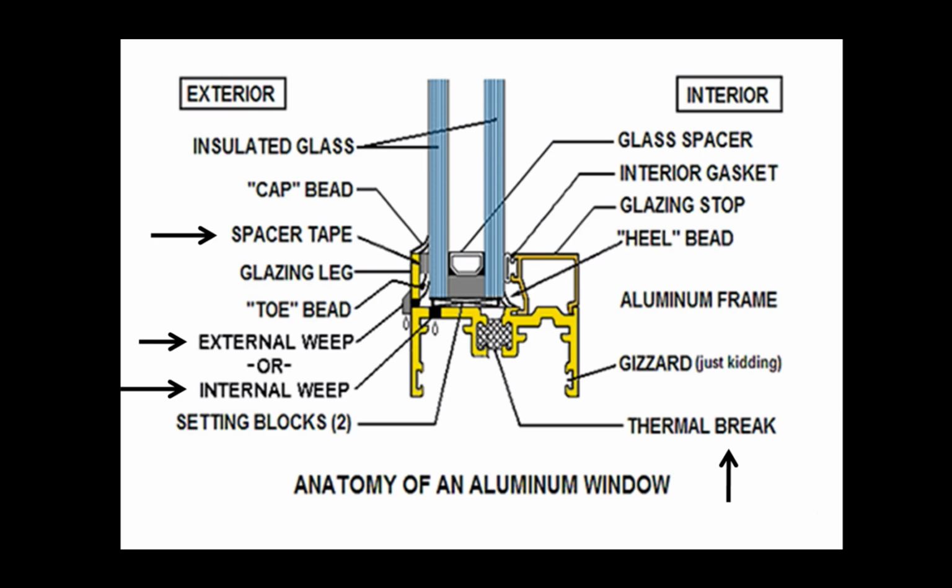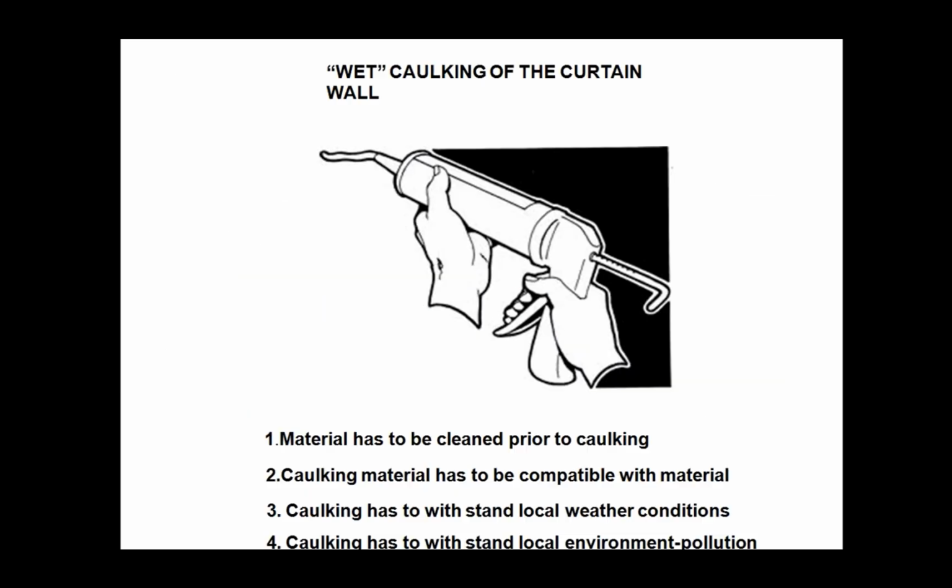And as you can see, it also has the same kind of gasket type system to make it a snug fit. So it's compressed against the window. And what this one has, it has actually small holes in the framing below it. So if water does get through, it weeps or drains into the lower section and then out. So just another typical cross section.